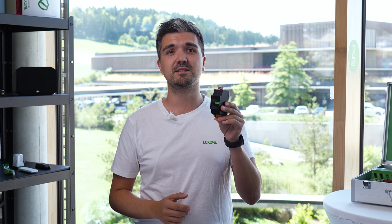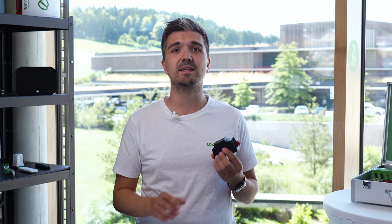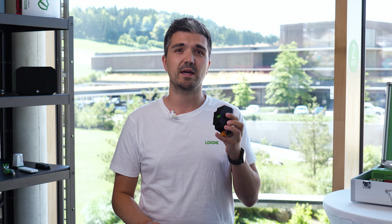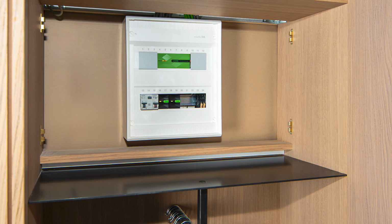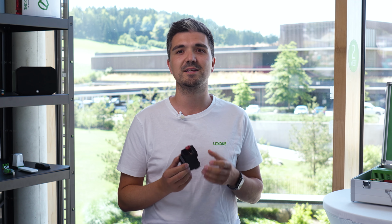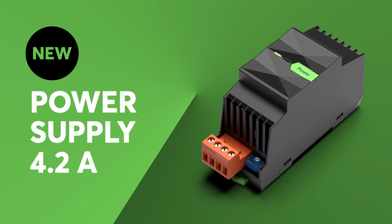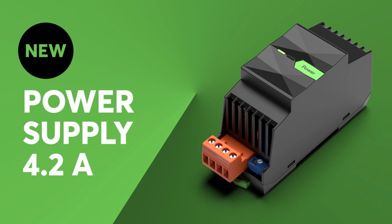Thanks! This is the new power supply with 4.2 amps. And it has a lot to offer. With its compact design, the same size as an extension, it delivers the same performance as the previous power supply, but with only half the space required. It mounts easily on a DIN rail and takes up 2 division units, perfect when space in the control cabinet is tight. Thanks to its built-in overload and short-circuit protection, it ensures a safe power supply.